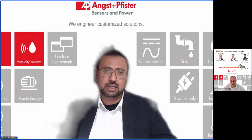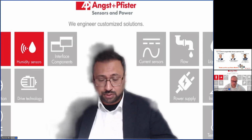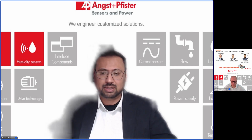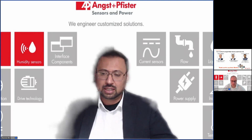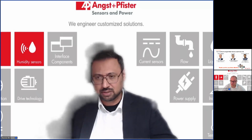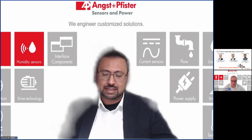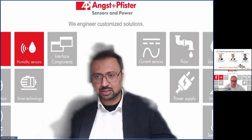And if the sensor is not behaving as it should, we have developed all three of these sensing technologies in a way that the user can recalibrate on site, without disassembling the sensor from the assembly, from the machine, from any application. This is exactly what we offer as a support to the customer so that they can calibrate the sensors by themselves. If not, we can also support it. Nonetheless, what we typically say is that the sensor should be calibrated once a year.